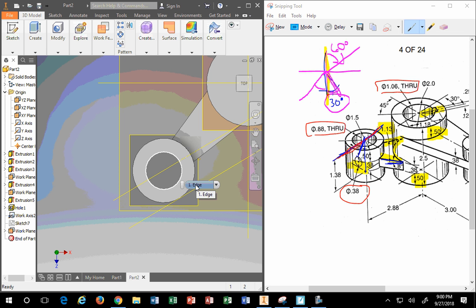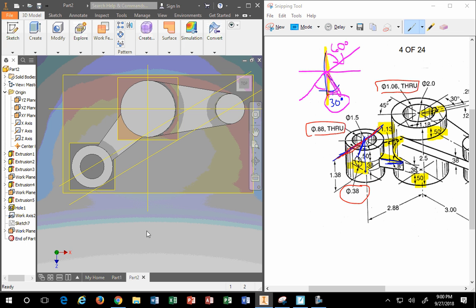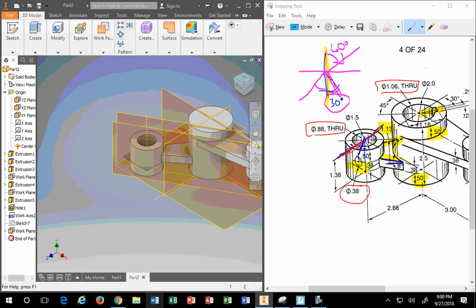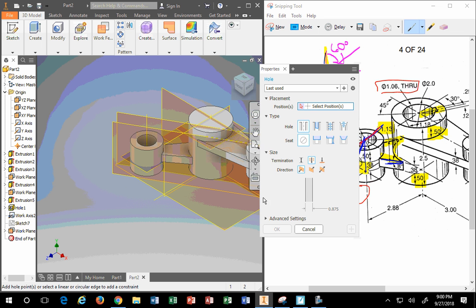I can make the plane parallel to that face of a cylinder if I have something to reference from to make that happen. And in this case, I chose to do it by putting a plane in. There you got it. So, this is the place where I drill my hole. I can do it right here on the face of the part. Because the hole command needs a place to go. It needs a plane, a face to attach to. What else does it need?